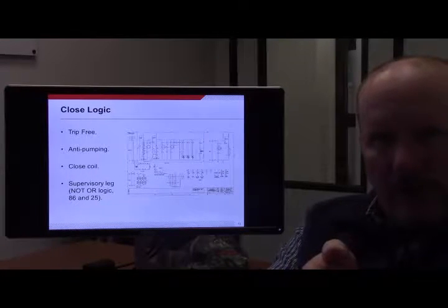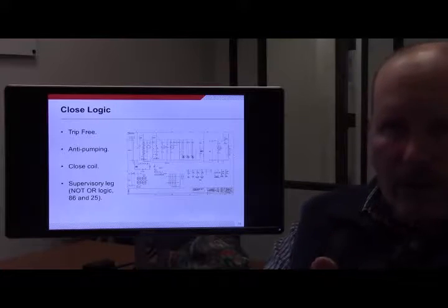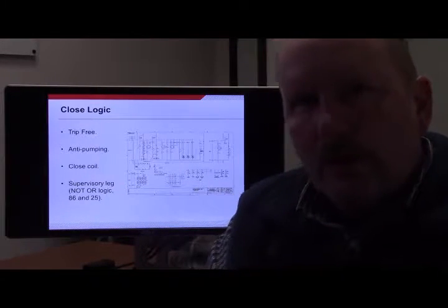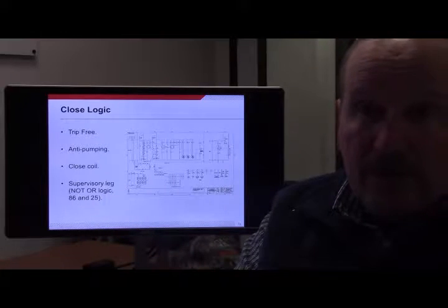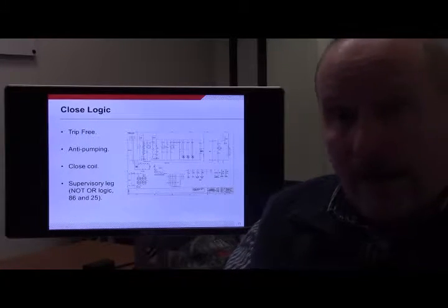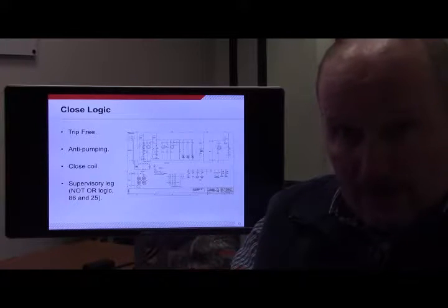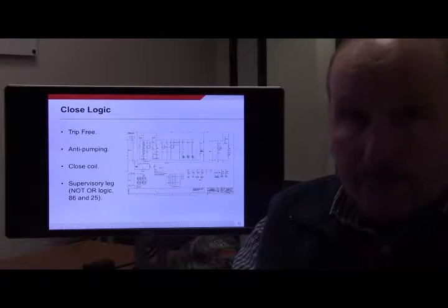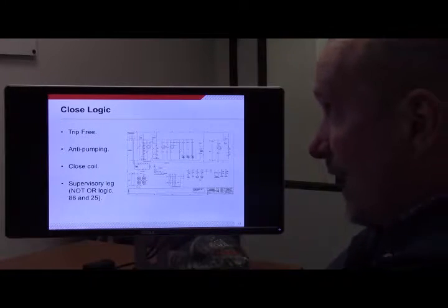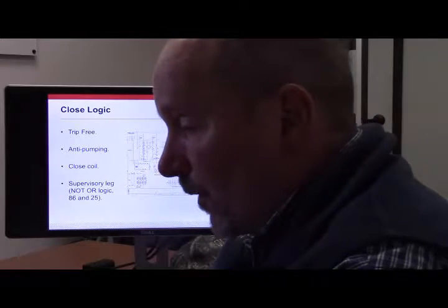You're holding those both closed. What you want to avoid is pumping your circuit breaker, when you trip, close, trip, close, trip, close. Because if you do that, you're going to wreak havoc on the electrical system, and eventually you're going to damage something in the circuit breaker, and it's going to stop working. So we want to make sure that we're covering that and seeing how we are able to control that system.